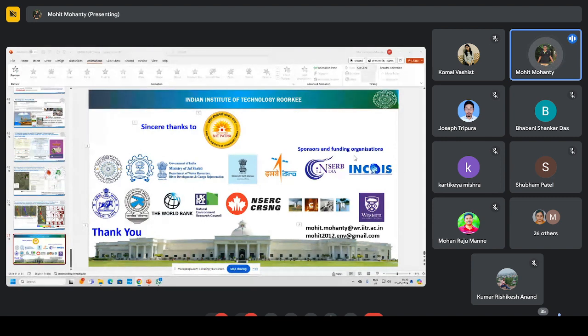So the flood model setup, we try to make more and more stable by considering a lot of other computational factors, for example the Courant number, which decides how stable the model is. When we create the model setup, we create a lot of grids, a lot of unstructured meshes. By tuning all these factors, we first make the model stable. Once the model is stable, we need to do a proper calibration and validation.